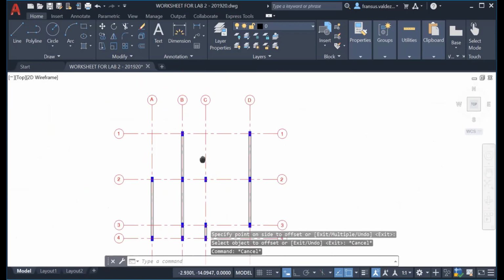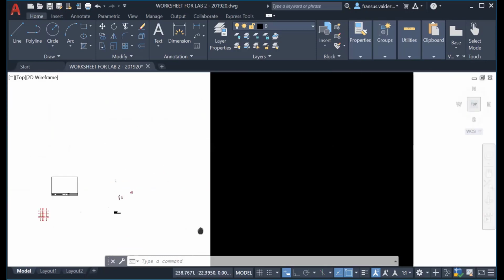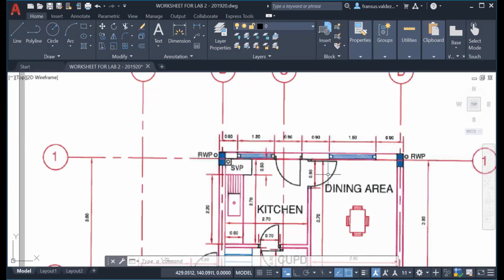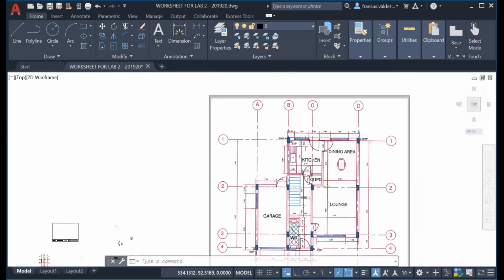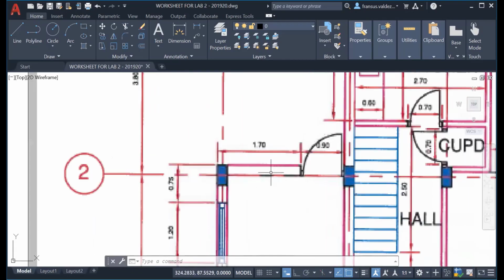However, along the horizontal, you will notice in the drawing, the external wall is from the grid lines, above the grid lines. It's not in the middle, it is above. However, the grid line 2, we have also an external wall which is above it.